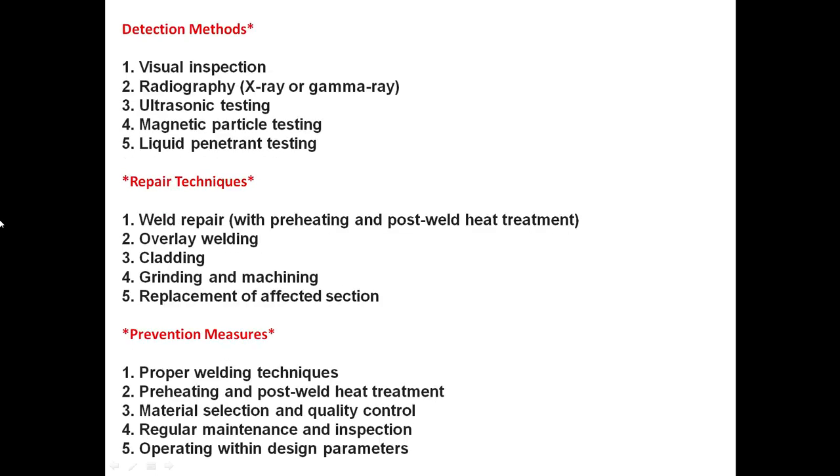Detection methods: visual inspection, radiography, ultrasonic testing, magnetic particle testing, liquid penetrant testing. Repair techniques: first, we can do the weld repair with preheating and post weld heat treatment. Second, overlay welding. Third, cladding, grinding and machining. Fourth, replacement of the affected section.